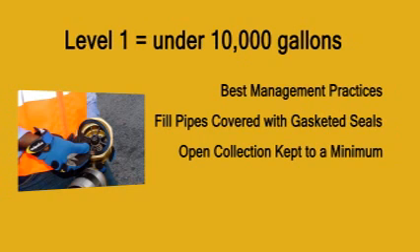Gasoline sent to open collection systems should be kept to a minimum. As for record keeping, you are not required to submit notifications or reports. However, you must have records that document your gasoline throughput and make them available within 24 hours if requested by the applicable authorities.